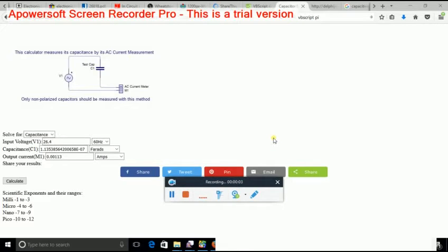It might not be able to do it that way because, for one thing, you have to put a resistance in series with it, because it probably will short out the transformer. Another thing is the way the reactance formula works, with the frequency so low, the reactance will be really low, lower than it is with capacitors.